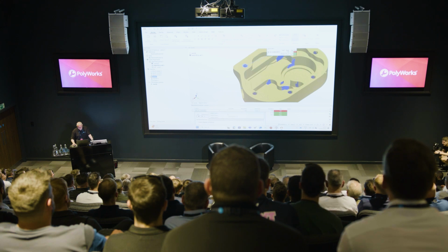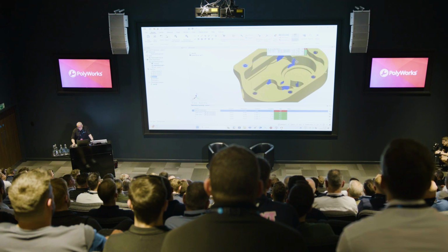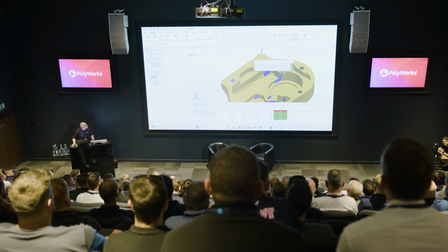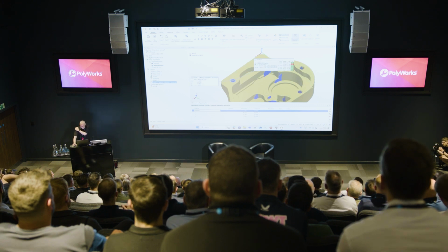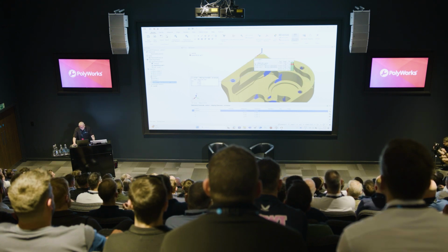And in there we can add in our derived dimensions. So in this case I'd be interested in the X and the Y errors. Now, previously what we might have done is we might have also added in the mating diameter for that. So we can go in and create the mating diameter, or we can do the X, Y and Z for the mating diameter. And this is exactly the situation we see. The centre X, Y and Z, the derived dimensions and the X and Y don't match.